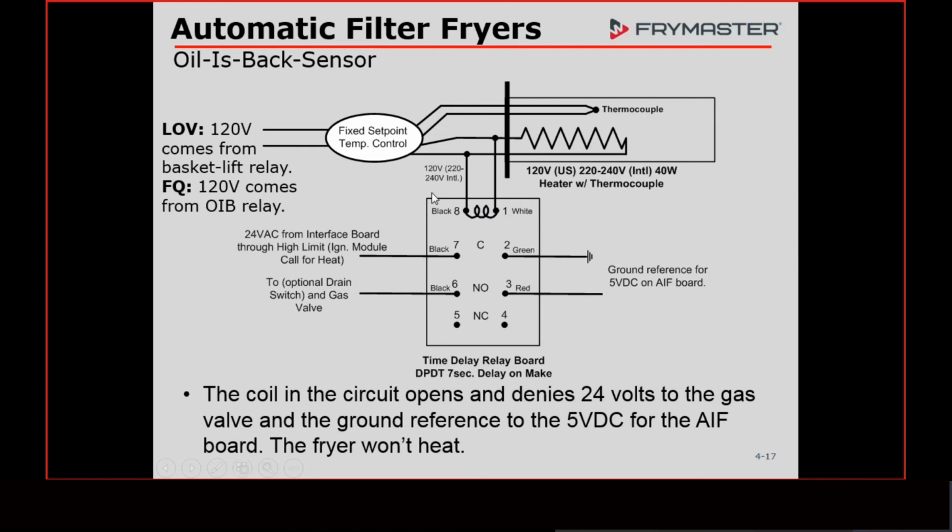That's how it works. I don't know if somebody here engineered this or where this idea came from. It works perfect for us. All right. Granted, there's float switches and things like that. Float switches and fryers don't work all that great. So this is a lot more reliable. Do these things ever go bad? Yeah, there's a heater in here. Elements go bad, and that's what that is. It's like a 40-watt light bulb. It's eventually going to burn out. All right, but as far as a big widespread problem, there's been some change, but hasn't been an issue.